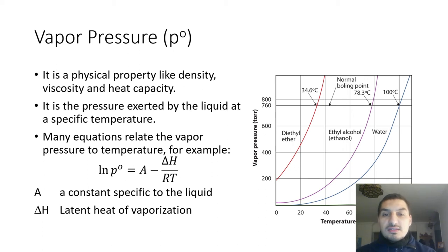And in this case, the water will evaporate at higher pressure because the outside pressure exerted on the liquid is not 760. It might be 800, 900, 1000. In this case, water needs to go to a higher temperature so that it can evaporate. And these pots are designed this way because sometimes you have something that needs to be cooked at higher temperature so that it can be cooked well, which is not going to be achieved at 100 Celsius. So it can reach 120 Celsius, 130 Celsius, because of the increase of the outside pressure.